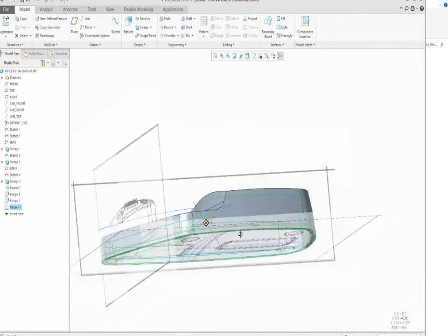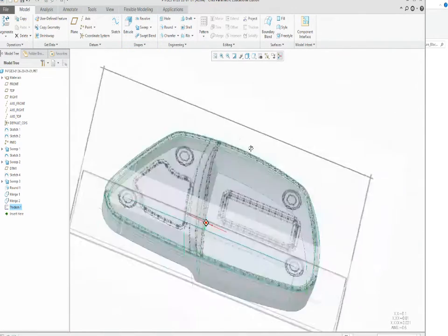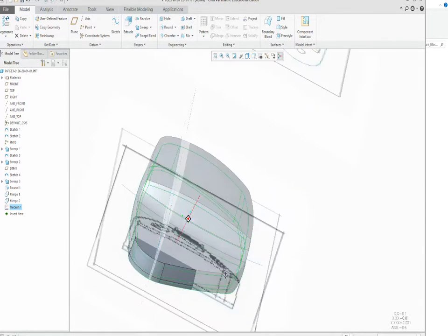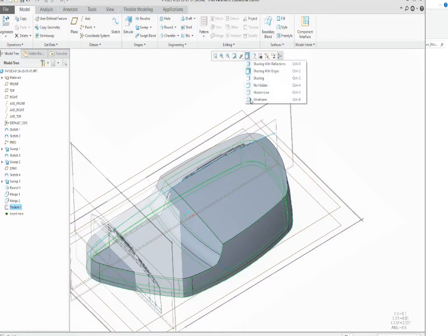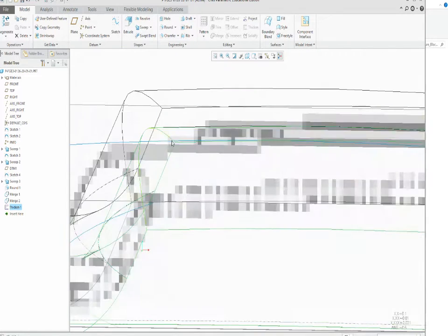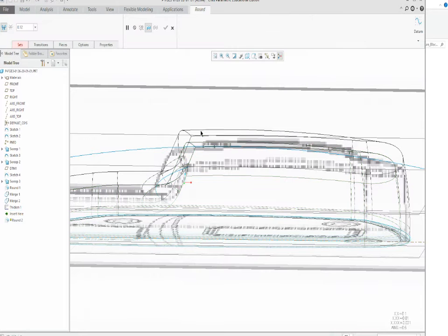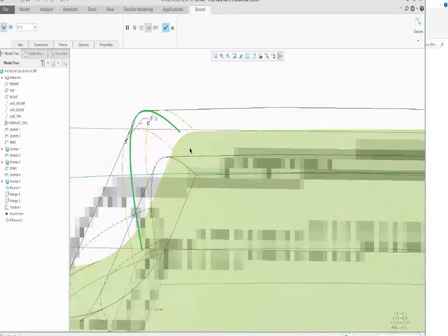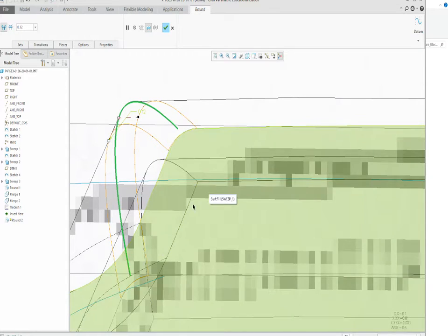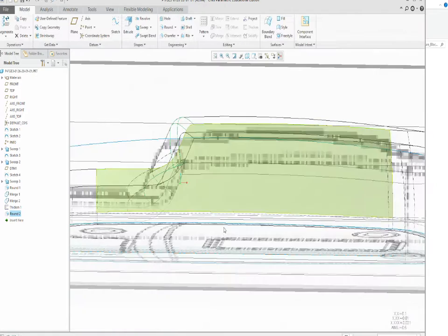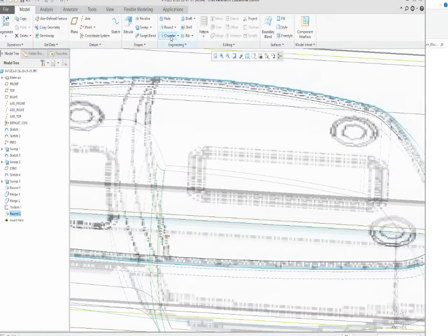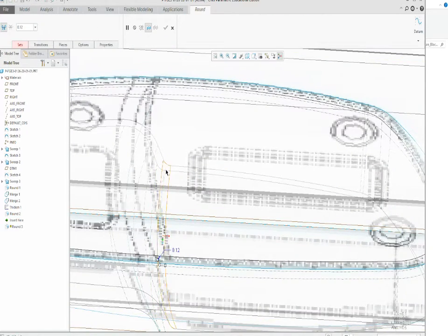If you cannot see it at this time, then what you can do is hide the images. But right now I'm going to go to wireframe because it's a little bit easier for me to see. And now I can see the inside and what they look like. So now if I want to put a large fillet here on this edge of 12 thousandths, then I add the 150, then I could get the other fillet on the inside. It would go down to 0 or nothing, but I would also want to make it easier for a ball end mill on the inside.